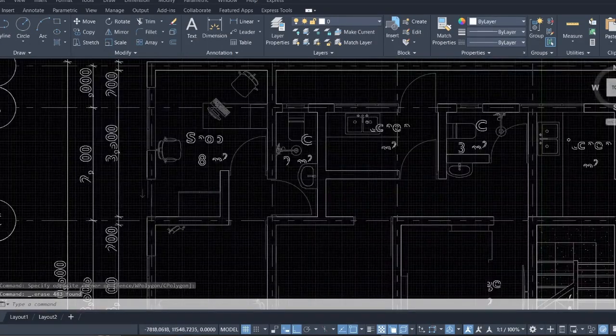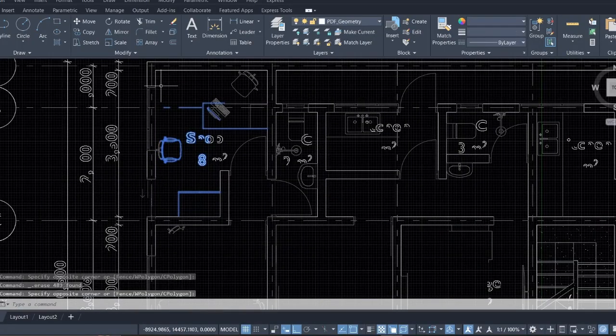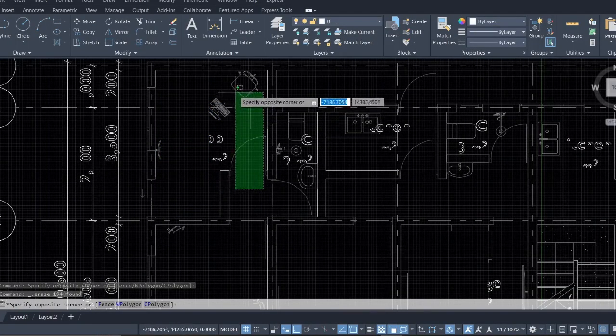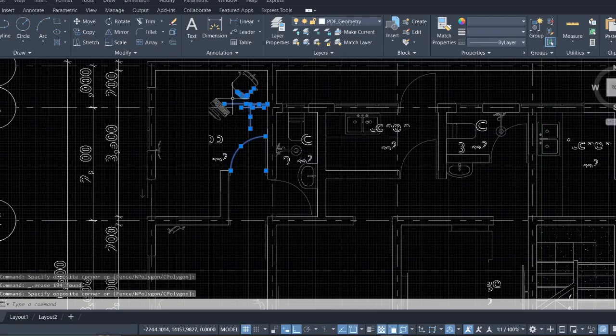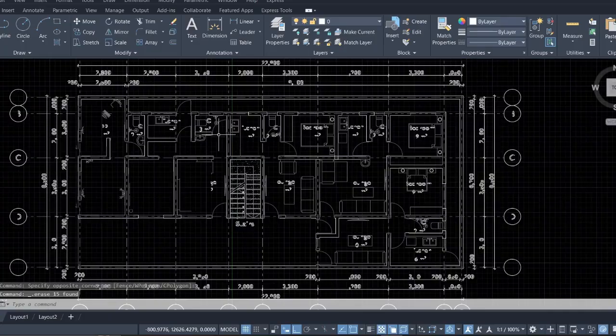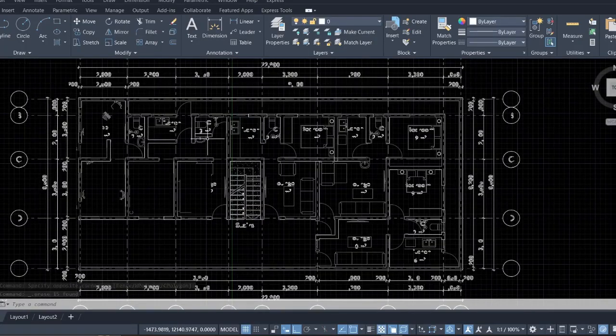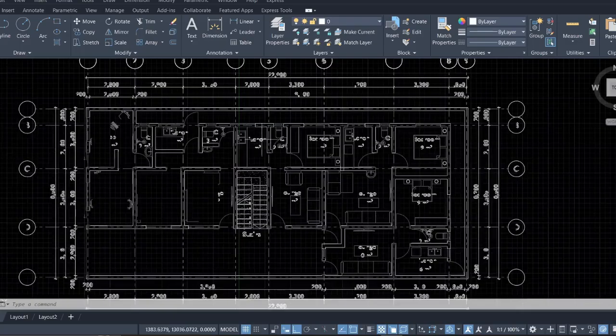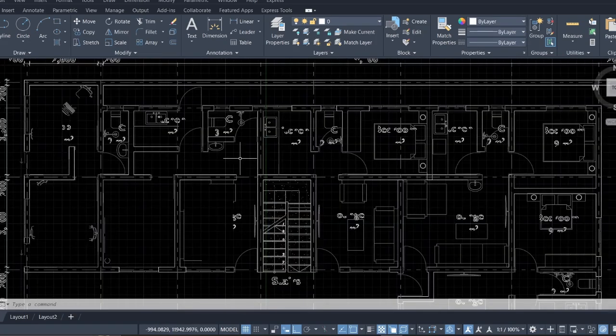So it takes quite some time to do these cleanups, but this is something that you can do as we go on. And remember that we even do not need what's referred to as this architectural grid, because we want to do our own structural grids. So it will be even easier to delete this once we actually add our grids and columns. So let's just proceed and do it.